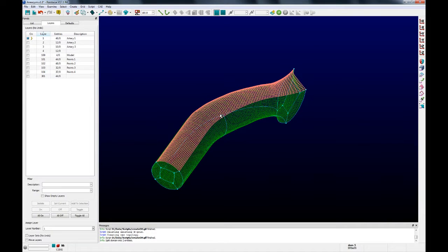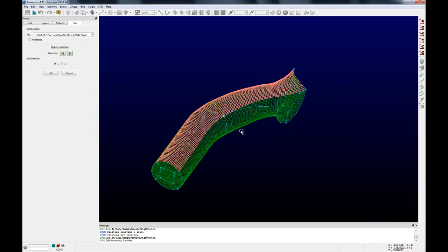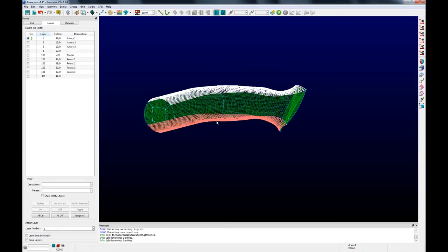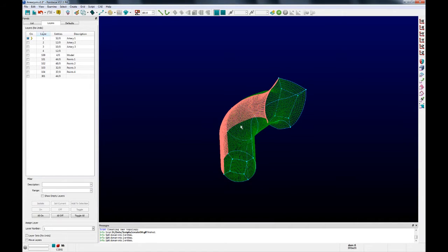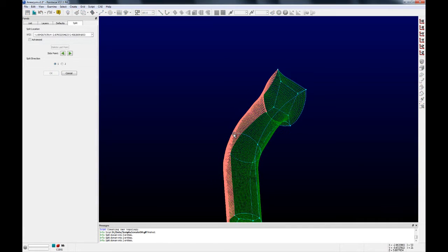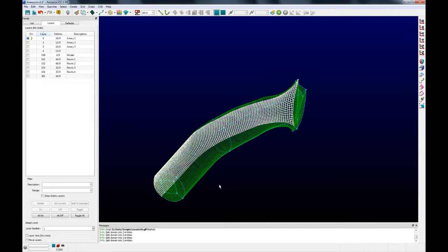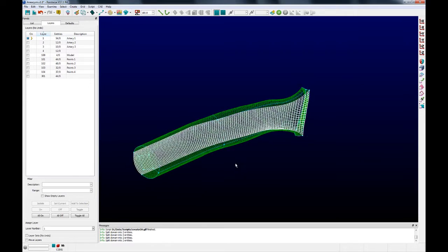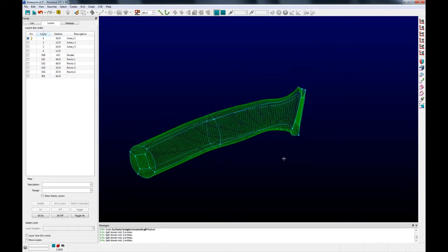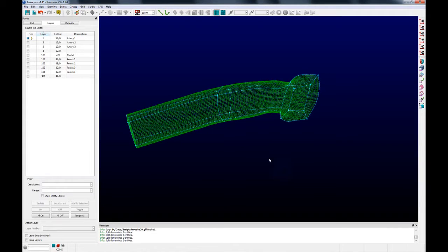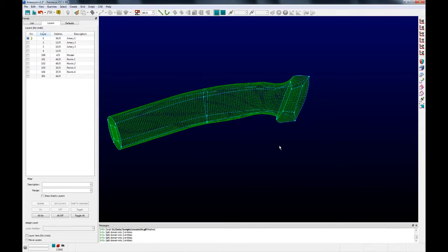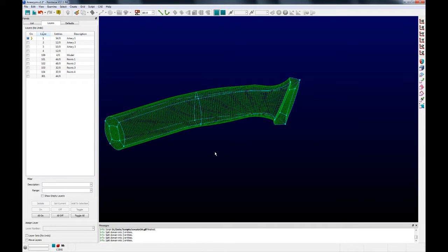We're going to repeat this using the accelerator, Control Q, for the other three domains, and that will allow us to divide this problem up into two portions. One at the entrance, where the artery inlet is over here, and then where the artery enters the junction. Whenever we're running the blocks solver a little later, you can see why it would be useful to isolate this region of high skew from this nice uniform region at the beginning.